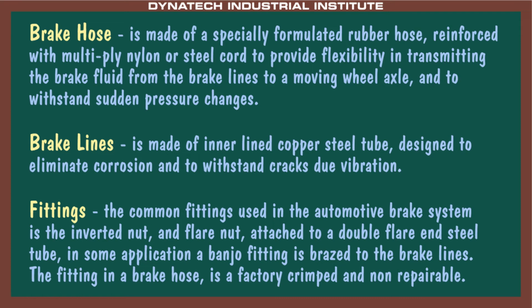Fittings: the common fittings used in the automotive brake system are the inverted nut and flare nut, attached to a double flare end steel tube. In some applications, a banjo fitting is brazed to the brake lines. The fitting in a brake hose is factory crimped and non-repairable.